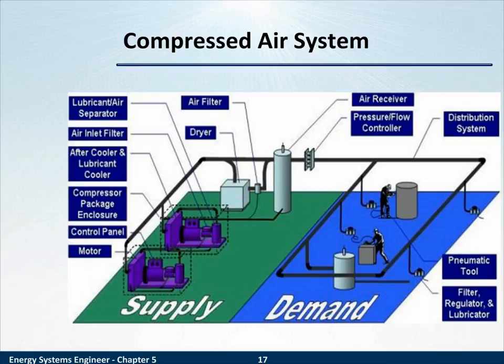Although this is a little bit of a cartoon, it includes some important characteristics and components of a compressed air system. This would often be considered a single compressor system, although there are two compressors, because there's one receiver. As you look around this componentry, there are opportunities for savings. Leaks, piping configuration, all those things we just mentioned are all included on this type of system. And like 50% of the facilities that responded had leak problems, not only is it the most predominant problem, it is also the largest energy cost with a compressed air system, as we'll see next.